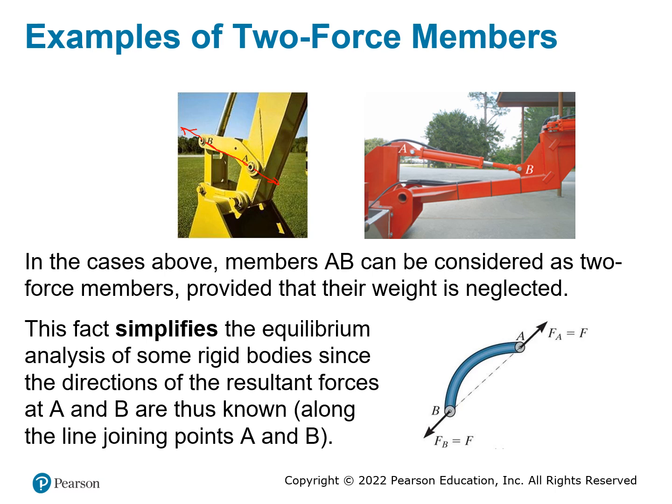Similar to that one, this red, I don't know, like a lift device here, and you have a hydraulic lift right here, and you have 2 ends, A and B. Again, this pin here and this pin here are the end points of this hydraulic device. And this will also be treated as a 2 force member, and then you can simplify this problem by summing their force in that specific direction.